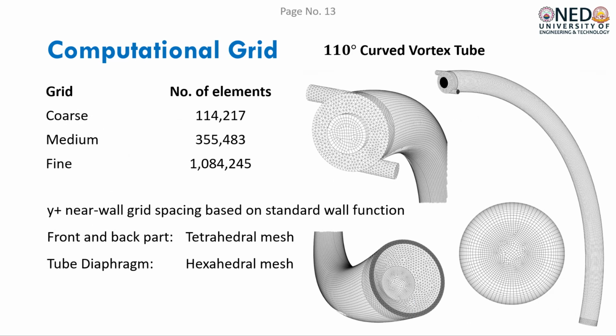An unstructured tetrahedral mesh is created with randomly distributed discretized cells of the geometry at the junction of the inlet and cold exit of the fluid domain. The hexahedrons are created across the swept area of both tubes. The quality of the mesh and the wall Y plus are two important parameters for generating the mesh, where the default Y plus requirement is set to more than 30 for the standard K epsilon turbulence model.